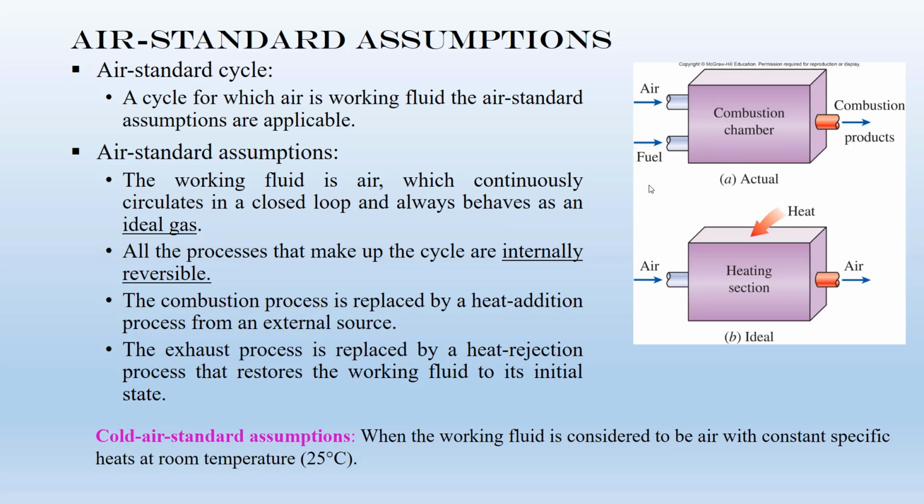And then you will see that in most cases this ratio, air to fuel, actually more than 90% of this mixture is air. So it makes sense to just assume that we have air in the inlet, correct? So it's a reasonable assumption to just cancel the fuel, and then we assume that we have air, and then you can use the thermophysical properties of air. This is the first thing.